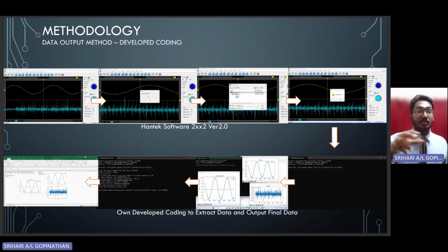My senior raised it up. So if you see the first row at the top, it's the data we can get from the software. But after many failures, I developed a code to interpret the data, and if you see that there's a wave over there, it's automatically interpreted from the transmitter and receiver waves also over there. The peak will be taken, peak to peak, and then at the end there will be an Excel sheet with the output of shear wave velocity and then shear modulus. Everything we need will be in the Excel.